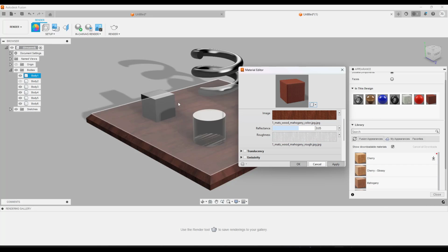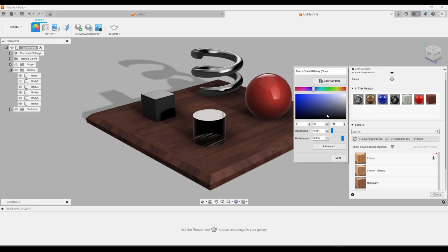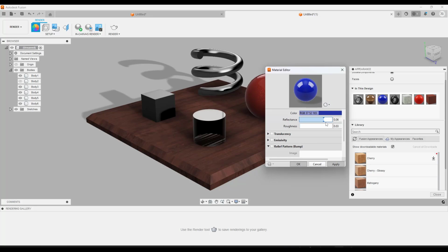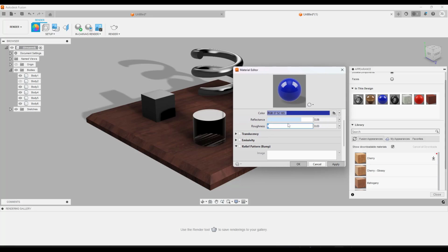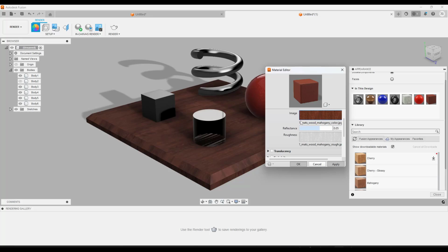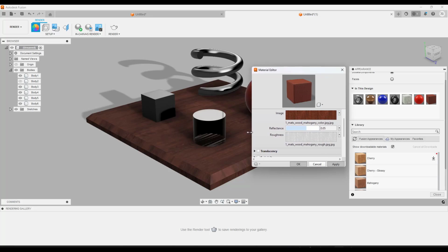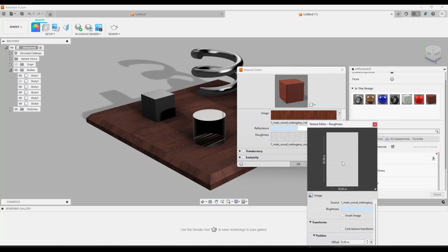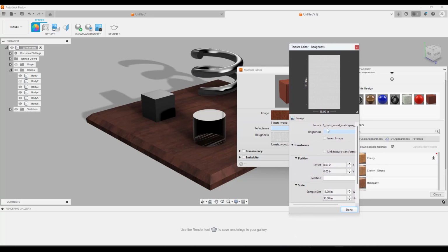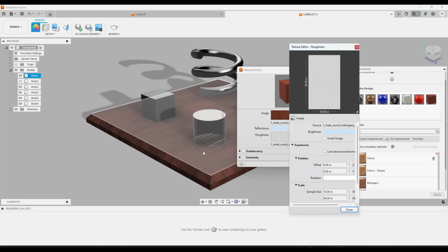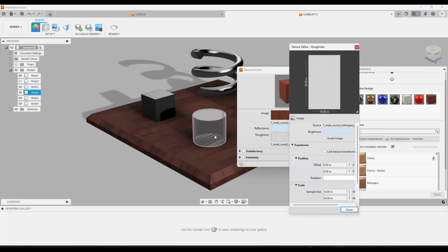And so instead of something like your paint material, if you go into your paint material and your advanced settings, it just has a roughness value, but there's no map because it's just kind of uniform. If you go into something like your mahogany material, notice how there's a roughness map in here, which is basically an image file that contains information about the way that light will reflect off of the object. This map is setting how much and where light is going to reflect.